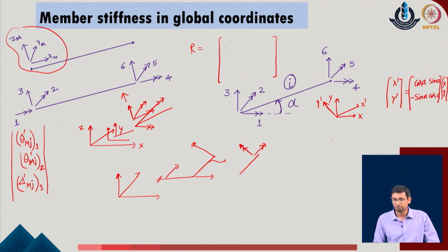Now we can understand that if everything is happening in the grid plane only, then whether you go with this direction of the moments or bring some new directions which are again in the same plane but located in two different directions, it works the same. One can consider that this is a plane of the grid in which there are two members. Rather than taking the moments in these two directions, I can just bring the direction like this. So now the moments are being taken along these two directions. So the rotation axis will remain the same, whereas for the z direction there is no change, because with respect to theta corresponding to the direction z, the normal axis remains the same all throughout.